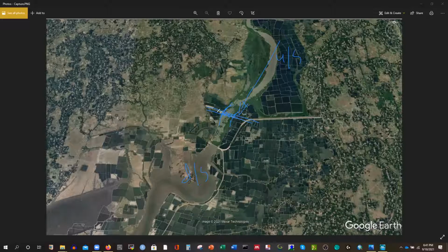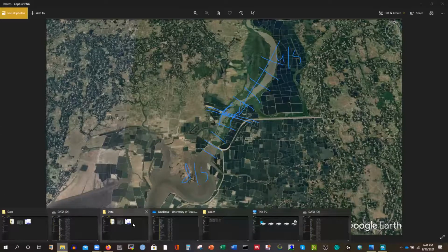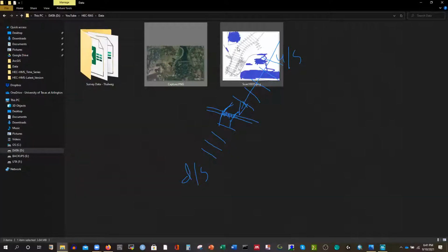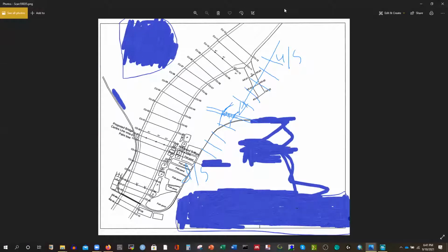We'll suggest that based on our calculation and the survey. But today I'm going to show you the real world case. We surveyed this river through a survey company, and they did the survey this way at 500 meter intervals. They took different cross-sectional readings using their echo sounding machine and survey instrument. So that's the plan for survey. I'm going to show you that plan. So here it is. Before surveying, they made the plan like this. Let me just quickly clear that, then you'll see clearly.